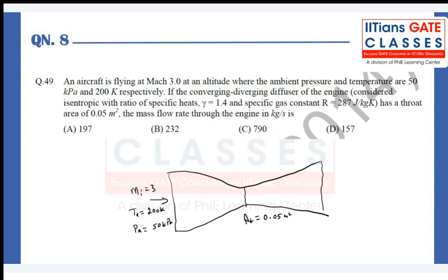If the incoming velocity is supersonic and you want it to be slowed down to subsonic values, that means somewhere within the duct we have to encounter a sonic condition, and usually the mathematics guides us to the minimum area of the duct where we can expect a sonic condition.